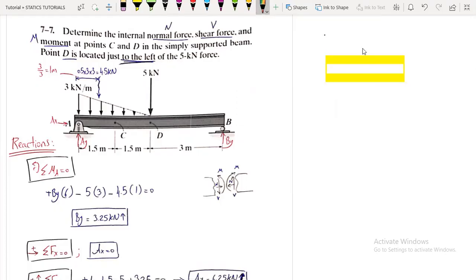let's say we have this beam, okay, and we have on it different types of loadings. Let's say we have a concentrated load, P, and say for example a uniform load, W, and say we have a fixed support, and this is a cantilever. So what's required from us is to find, at a specific point, let's say here it is C, the internal loading.